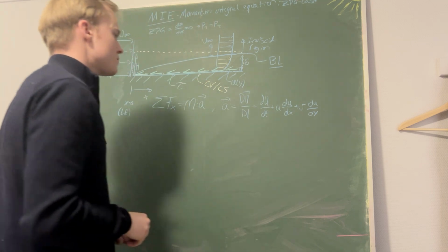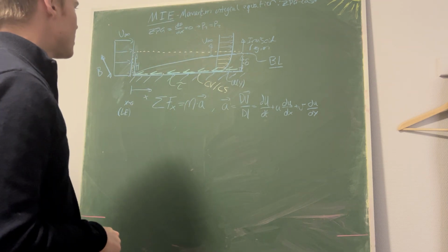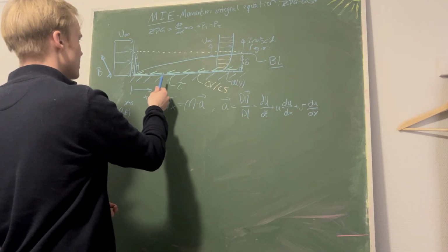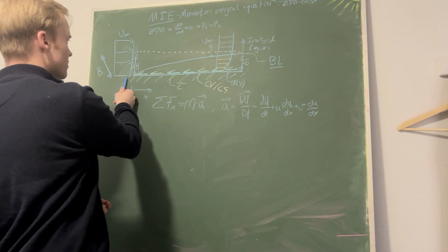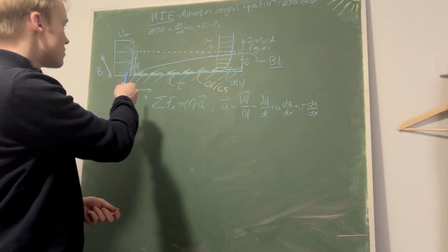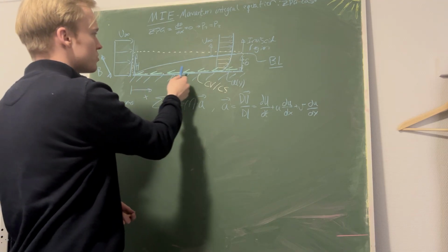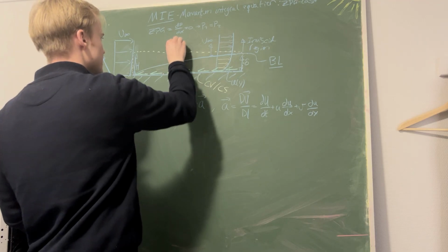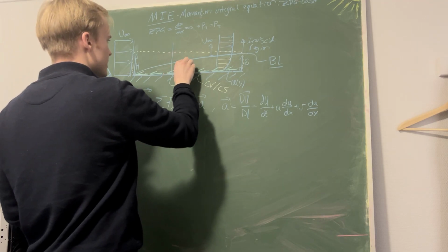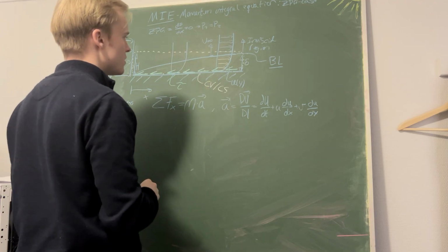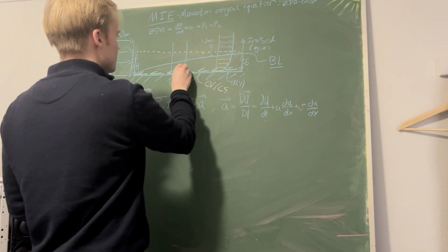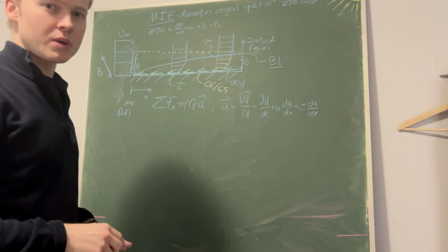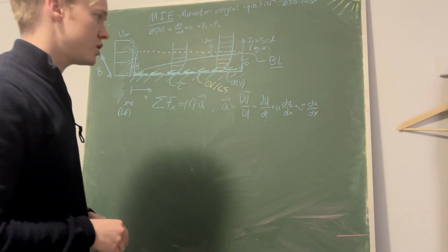Right? But now the thing is that we know, because we have shear working in this case, that the velocity profile we send in here, which is a uniform flow profile, is going to change, as we see here. It's going to develop. So, for example, at this distance here, we might have something looking like this, okay? So the velocity profile is changing along x.